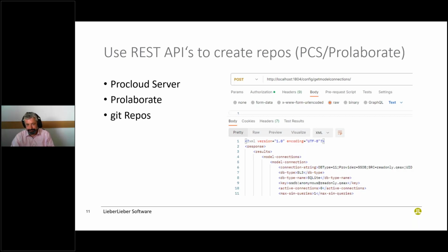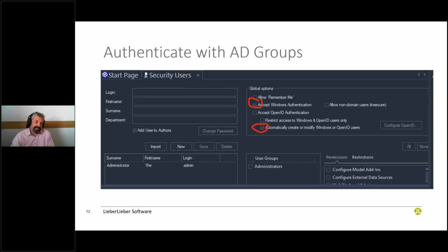Another very simple example that we see very often that is not used: I can only talk for me, but I think it's a waste of my time to maintain users and groups in Enterprise Architect. Why not do a one-time operation, accept Windows authentication, and link the groups to Active Directory groups, and use the Active Directory and the Windows authentication to authenticate people against my model.